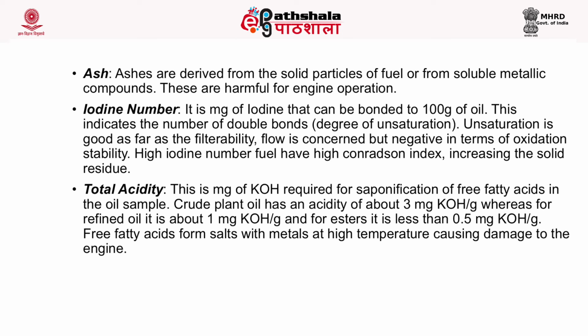Now next is the total acidity, and this is the milligram of KOH required for saponification of free fatty acids in the oil sample. Crude plant oil has an acidity of about 3 milligrams of KOH per gram, whereas for refined oil it is about 1 milligram of KOH per gram, and for biodiesel it is less than 0.5 milligrams of KOH per gram. Free fatty acids form salt with metals at high temperature causing damage to the engine.